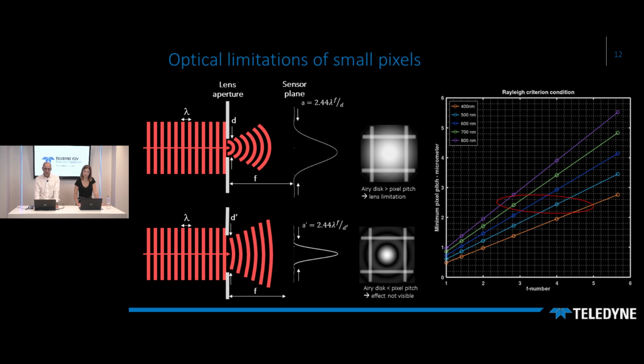So if we consider the main optic, it produces a well-known diffraction pattern. This pattern is projected on the sensor plane, and the spatial resolution of this pattern, called the Airy disk, is non-uniform as described in the figure on the left. The diameter of the circle is proportional to the wavelength and the f number. As the Airy disk grows, it eventually covers adjacent pixels too, producing blur in the conditions of the scheme above.